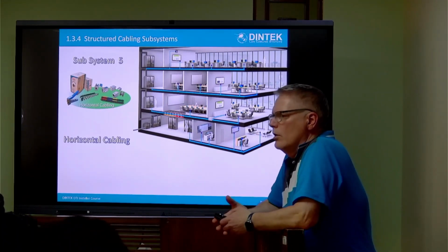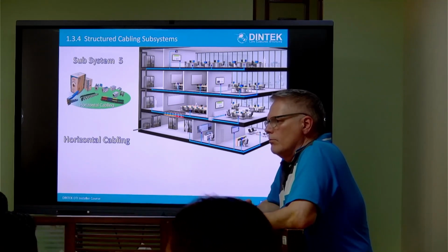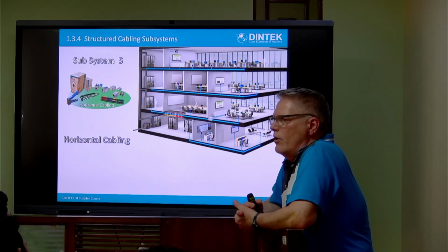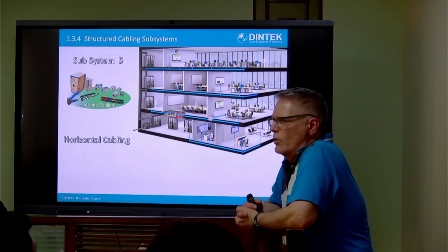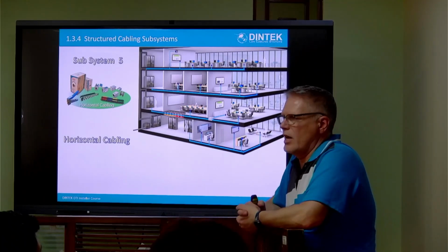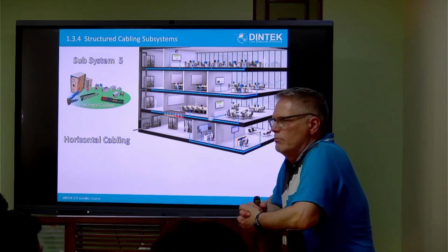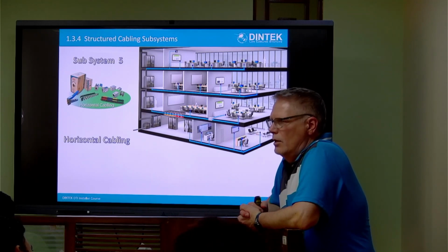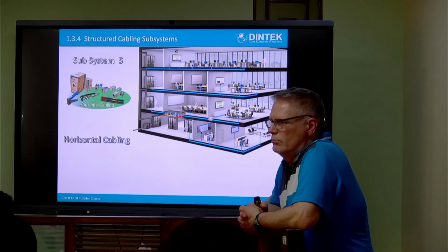Is the degree Celsius for technological room or server? Both. Well, the standards state that an environmentally stable condition for electrical equipment is about 20 degrees Celsius. So when they say it should be environmentally stable, they just go back to what they rate as being environmentally stable, which is 20 degrees. That's not a definite, but that's under the standards. They're saying this will guarantee that you won't have failure on this.